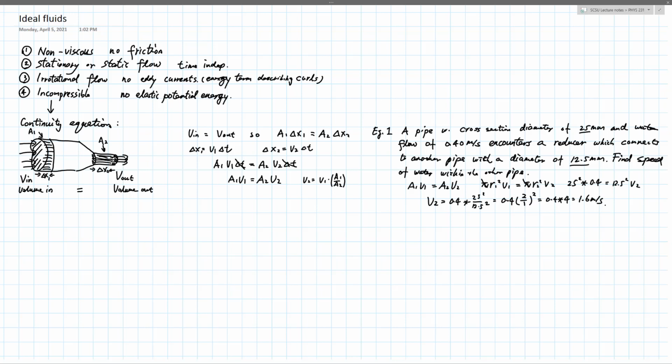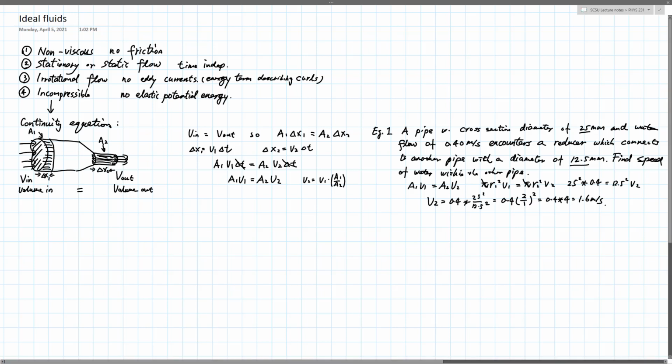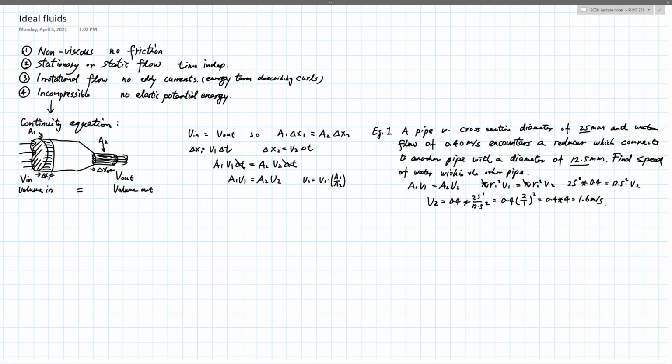Well, where does it hit? It's a projectile motion problem. You have to find the initial velocity in order to find where it hits. And the initial velocity is not where the water is flowing through the thicker pipe. It's where it flows through the thinner one, because that's where it is let out into the air to become a projectile.